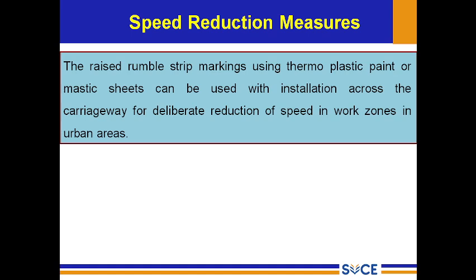It's well proven in India. Nowadays, on major roads like national highways and expressways, where you do not need much reduction of speed, the speed is the main criterion where they are using this kind of rumble strips. In foreign countries, the rumble strips are used on the side of the road during night time, especially at curves, so the vehicle should not go out of the curve. In such cases, this gives a vibrating effect, so the driver gets alert even if he sleeps. He will come to know that the vehicle is going out of control. So for that also the rumble strips are used on the side, the edge of the roads.